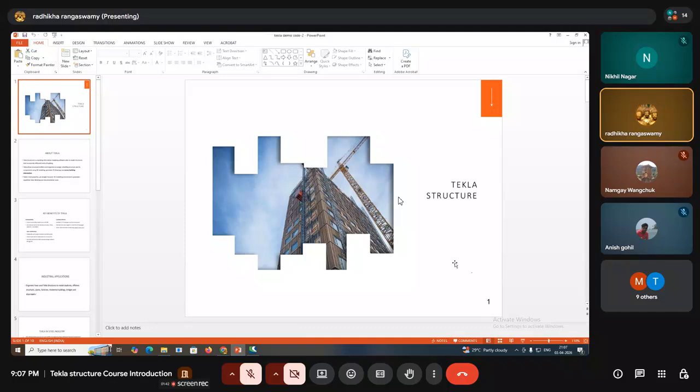The thing here is, in Revit software you can create the architecture model, but you can't extract the real-time detailing concepts and the real bill of materials from Revit. Clear? Because when you're giving the fabrication drawing to the factory, you can't give the Revit details to the fabricators to create the drawings for the complete real-time structure models. We can't give the input details as they are. So in that case, how can we give it in an effective form? By using the Tekla Structures software, you can give it.